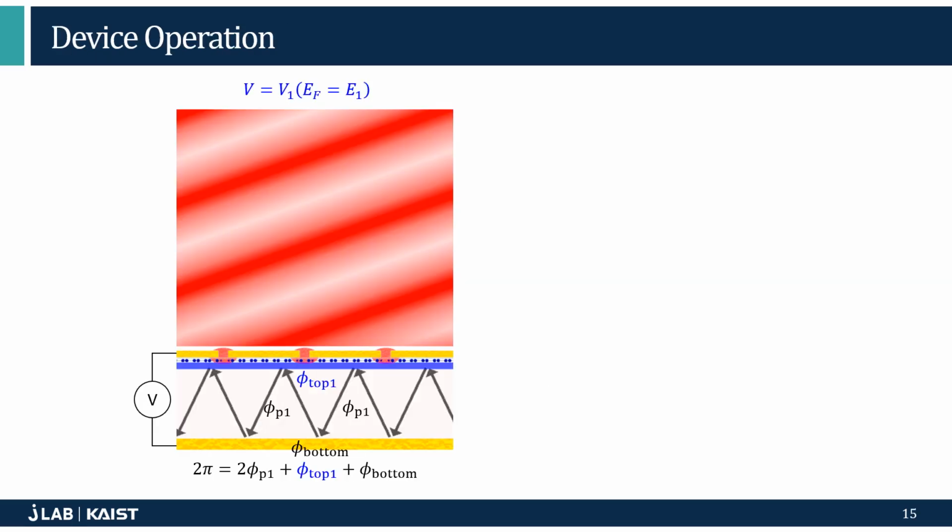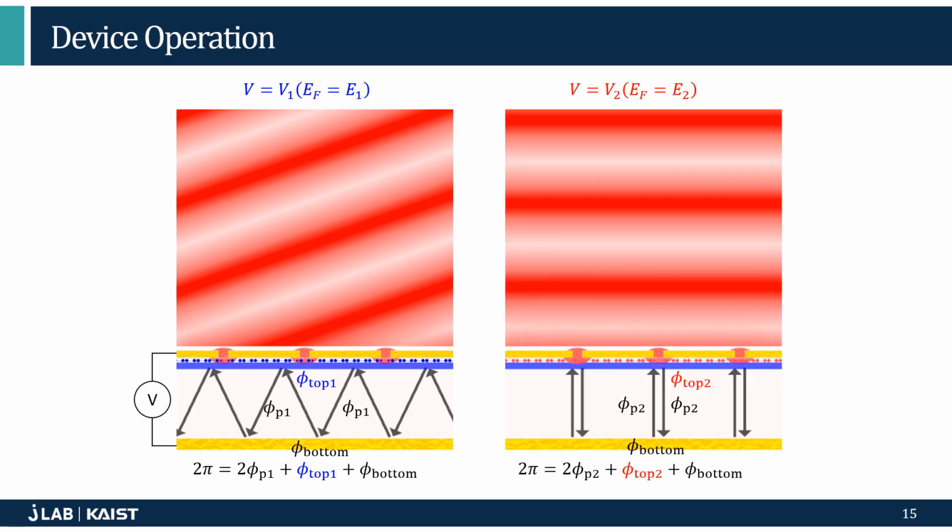Based on this, we realize this tunable mirror by using the graphene metasurface, and at a given graphene status, the reflection phase is fixed, and the oscillation direction and emission direction are given like that. And if we change the reflection phase, then as I said, we modulate the oscillation direction, and following this, the emission direction is also changed. This is the principle of directional thermal emission steering. Next, I will talk about the design of this metasurface and structure, and also the experimental demonstration of our work.